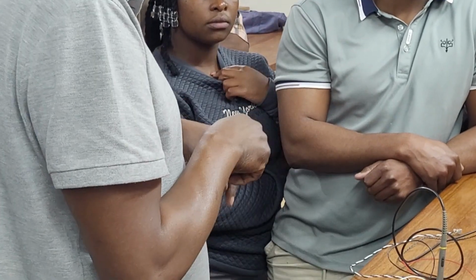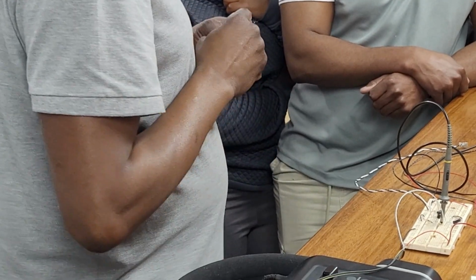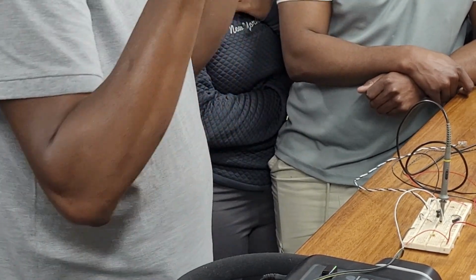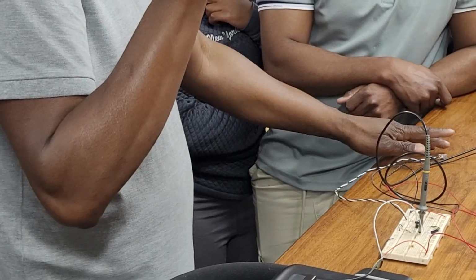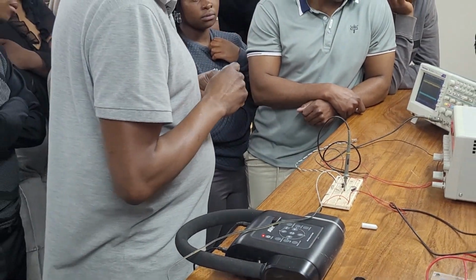Okay, and another thing, by the way, I did say to you, if you remove that capacitor there, the 47 microfarad, which is this one, you reduce the gain. You can just demonstrate. I just pulled it out. It's no longer doing what it's supposed to. It is still there, but at a much, much reduced gain.